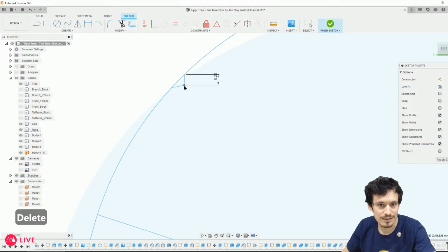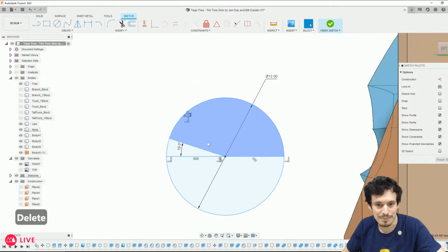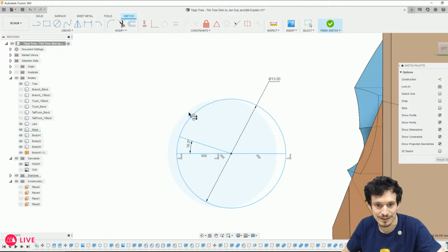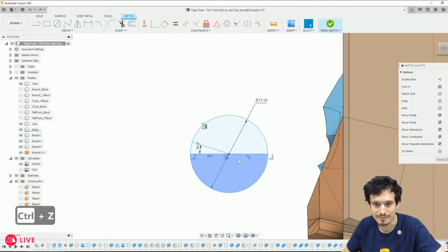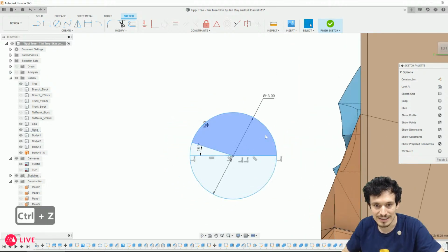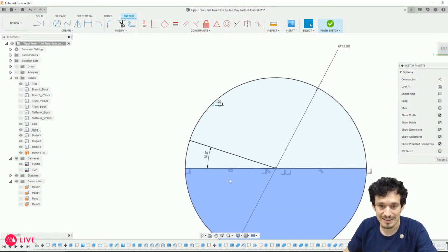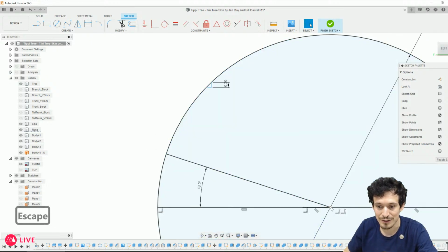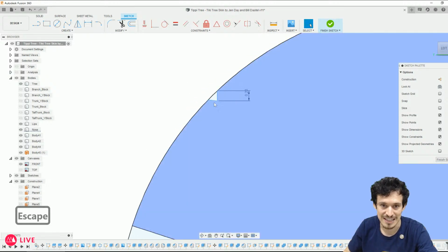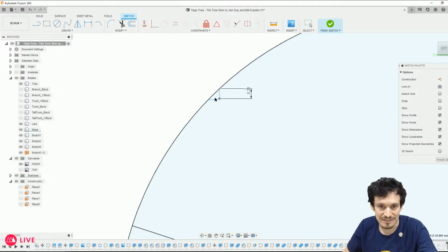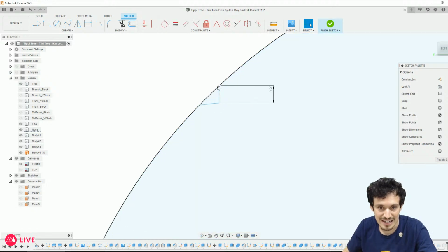Whoa. See, this is what happens when you don't fix things. You try to move this little dot and you end up moving everything. We can just select the center point and fix it, which isn't the most technically correct way to do things. You usually don't want to just use that fix command. You're better off figuring out exactly how to...